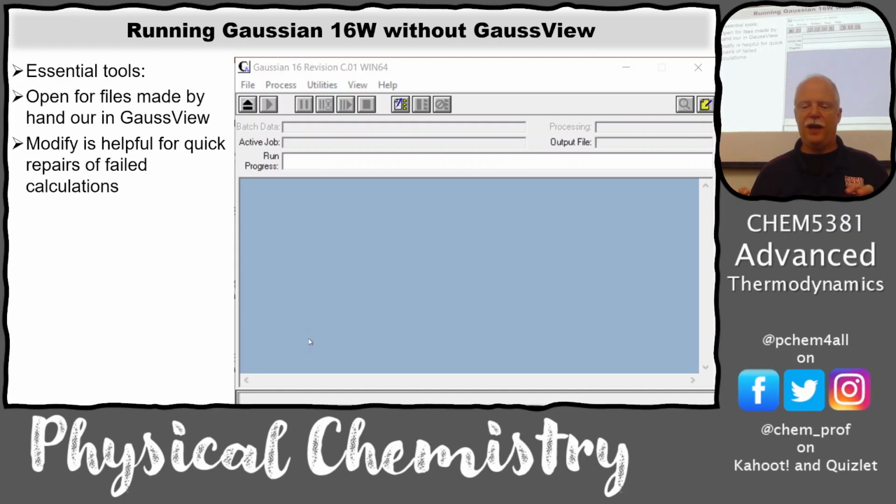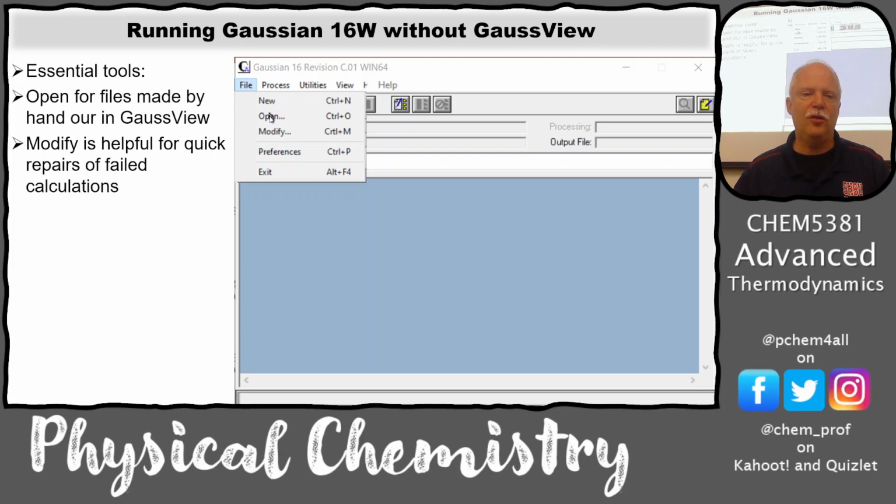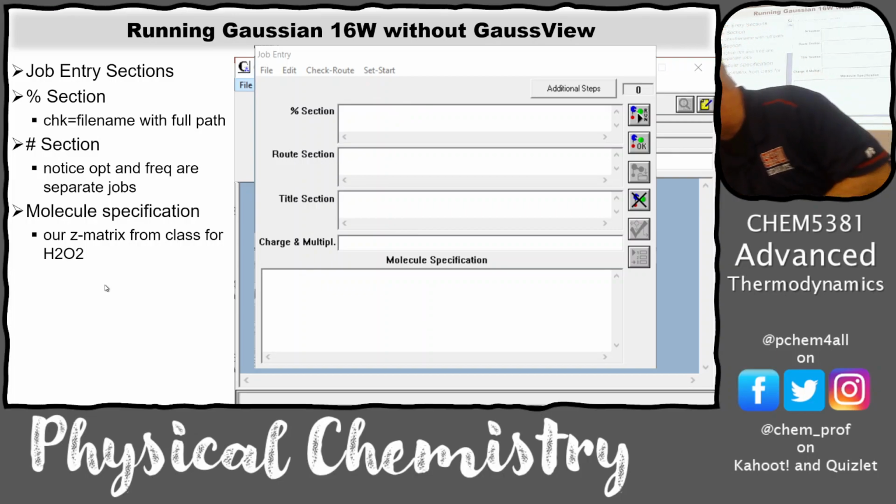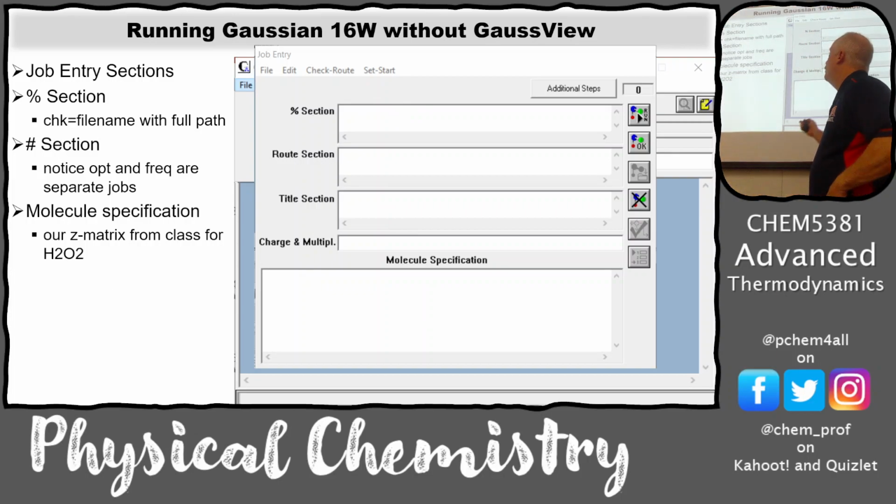Sometimes it's helpful to modify or to be able to start and stop calculations using Gaussian without GaussView. So this is the Gaussian window. Okay, you go in here, File, Open, and you get this section, or File New, you get this section. And here's what I was showing on the board at one time. I was showing the percent section, or I called it the percent card, or the root section, the root card. That percent and root sections have to start with certain characters. So it starts with the percent sign or the pound sign, or hashtag as we call it now. And so then you have the molecule specification section here, and we'll do charge of multiplicity.